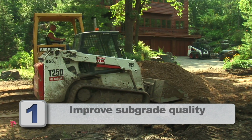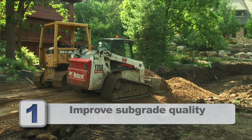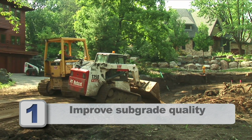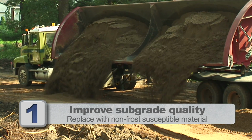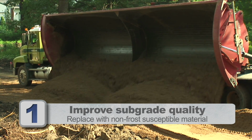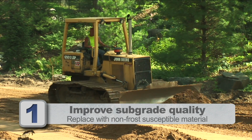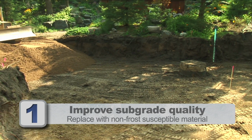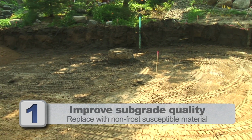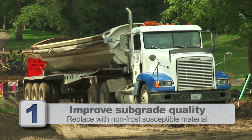One is to improve the quality of the subgrade. For areas with non-uniform subgrade soils, the most comprehensive approach is to remove the frost-susceptible soil and replace it with non-frost-susceptible material. Many agencies require replacement material with no more than 5 or 6% fines. The material must be placed deep enough so frost is unlikely to penetrate to the materials underneath it. That depth will vary depending on local conditions.